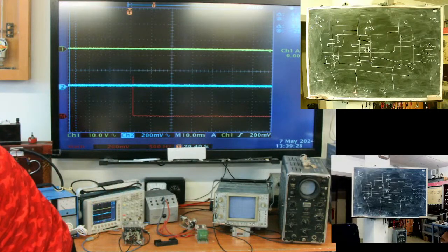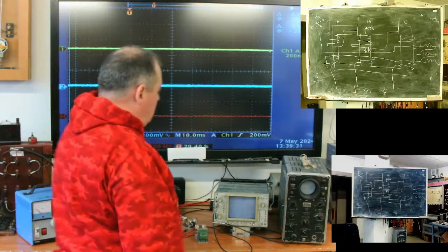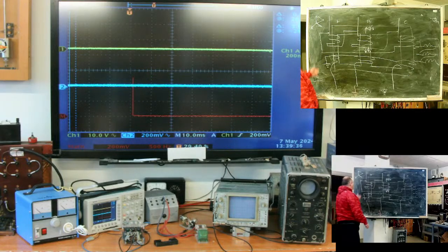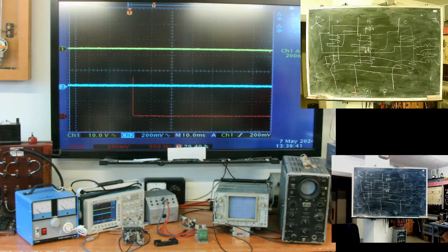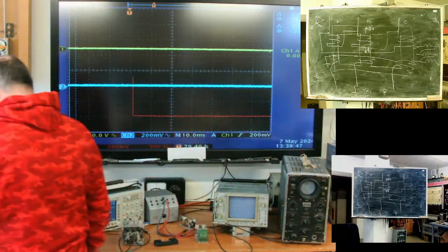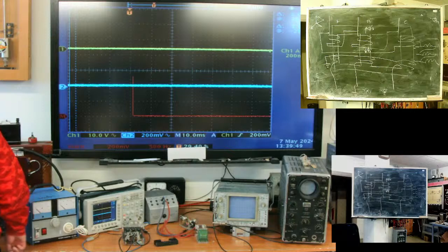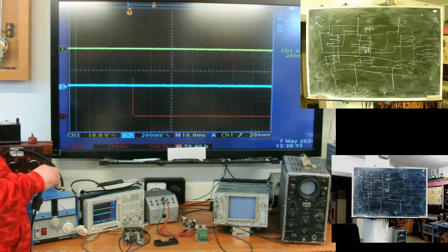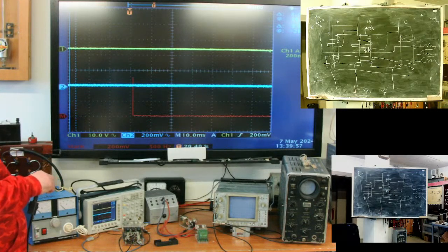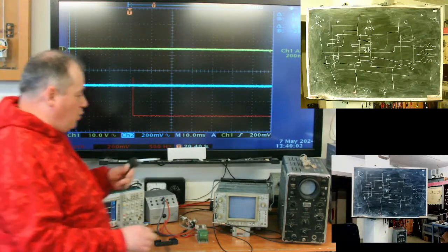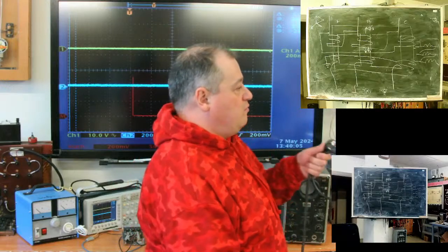But the third harmonic in the flux induces 150 Hertz current in the delta. It circulates and produces 150 or third harmonic flux directed against, demagnetizing the core. For such a transformer, there will be no distortion in voltages.